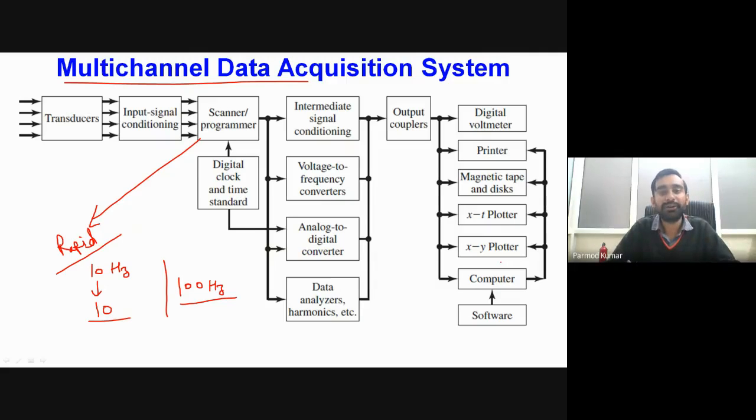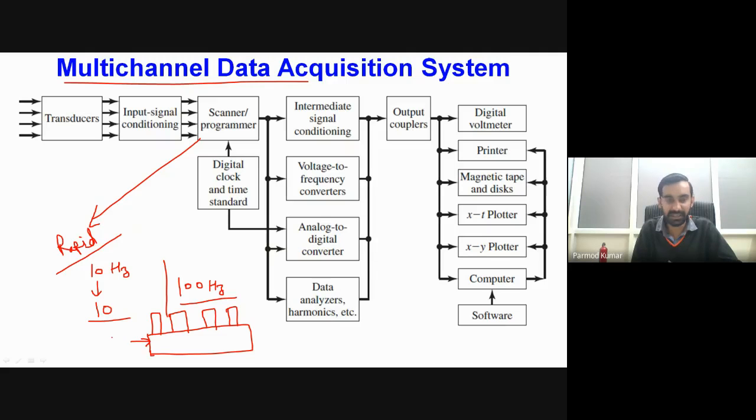Okay. Now, one of the more generalized systems available nowadays has a single module, and in this single module we can employ a number of property-specific modules. For example, if we have a single generalized system, it will connect our transducer to our computer or a software where we are acquiring the data, and over this generalized system we will have individual modules depending upon the output type of our transducer.